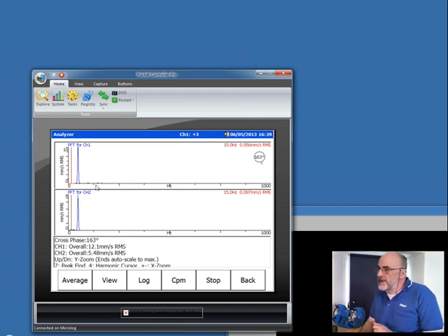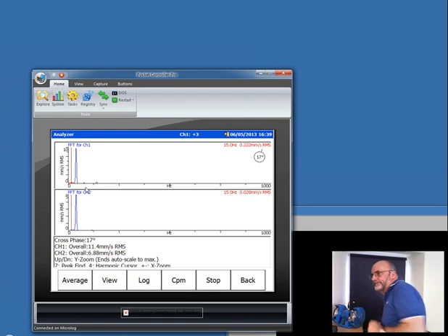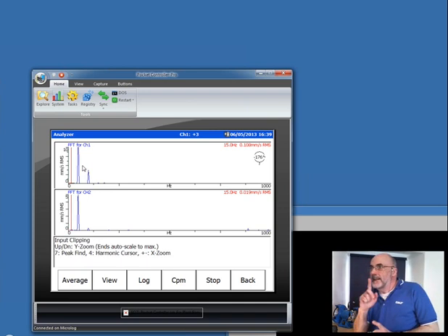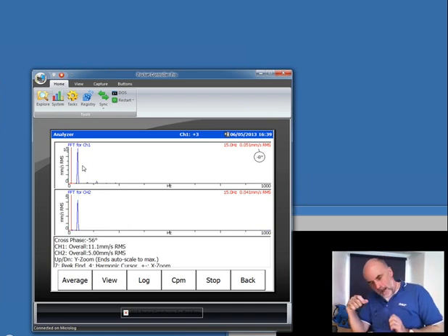It disappears instantaneously, and I'm just left with the unbalance. There's the unbalance getting slower and slower and slower, and my machine's running down. That 2 times has dropped radically. If I switch it back on, you'll see it reappear. Comes back instantaneously and disappears instantaneously. That is classic electrical type issues.